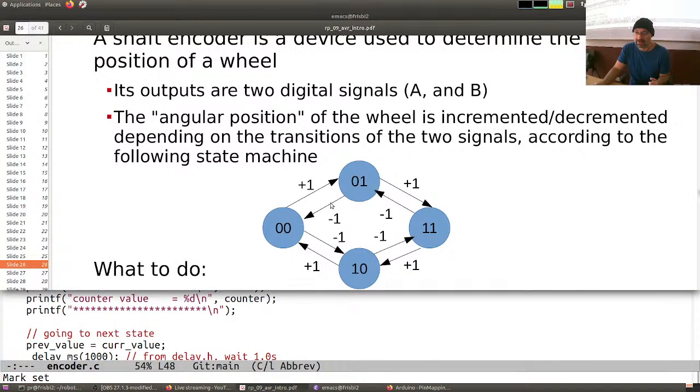we figure out that the transition is entirely indexed by the 2 starting bits and the 2 leading bits, right? So I could have actually 8 transitions, or I could have a lookup table which was indexed by the string composed by the starting state and the leading state.